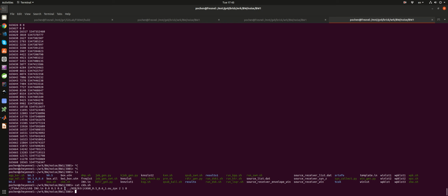And then the last number is going to be the amplitude of the perturbation. For now, it's just a 1, right? So the checkerboard is going to vary between plus and minus 1, basically. If you want a bigger amplitude like 10 or something, or a smaller amplitude like 10 to the minus 3 power, that kind of thing, then you can just change this number. So that's going to give you a checkerboard pattern that has a smaller variation amplitude.